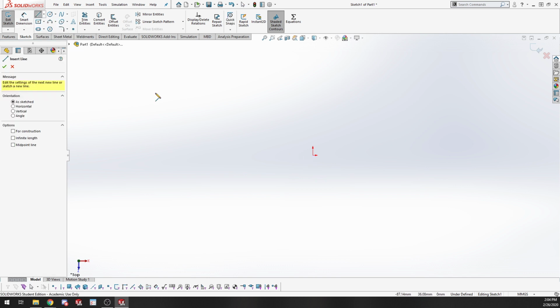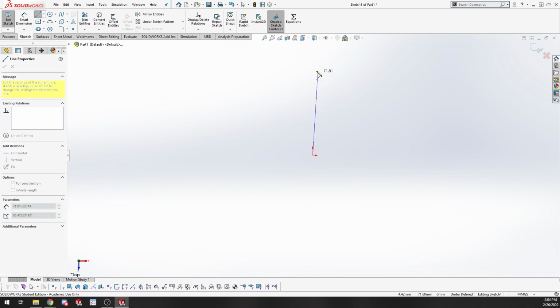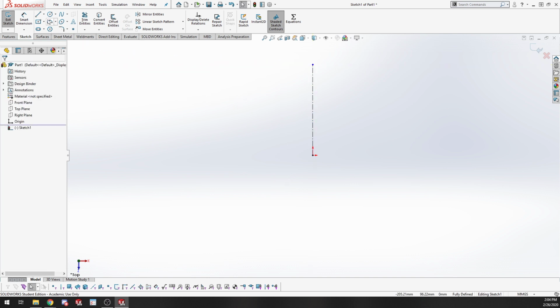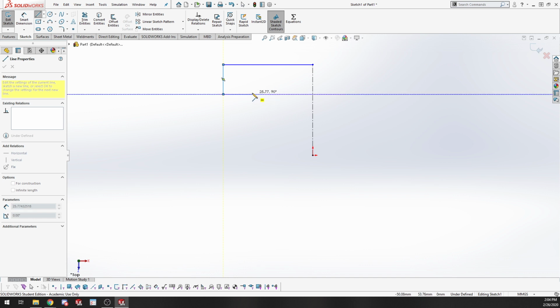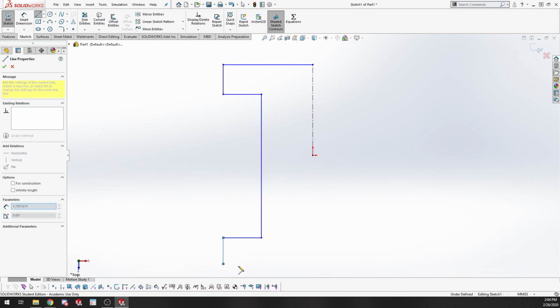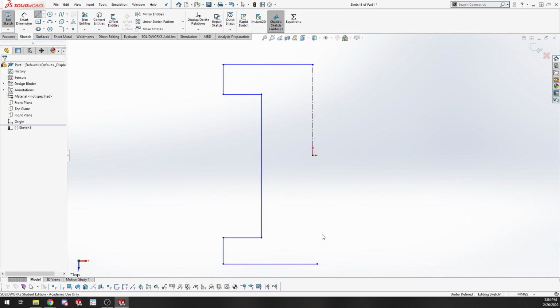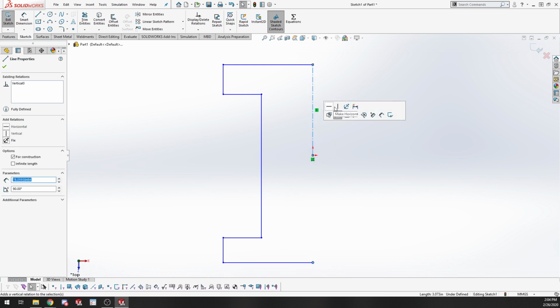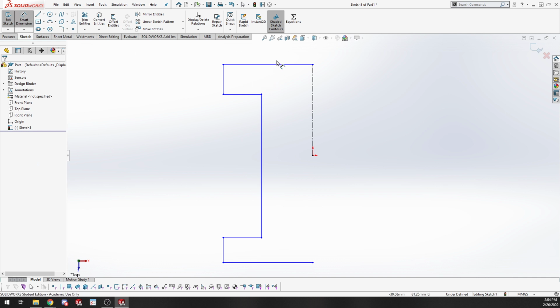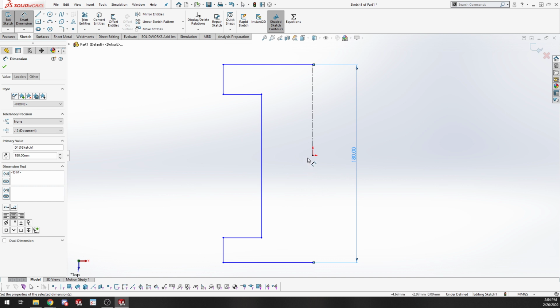So a simple construction line to start, and then, because the center of the steering wheel is a fairly simple shape, there's where my first grips come out to. I'll just make it super simple here. Just going to have 2 grips. I think the steering wheel that I designed was like 200, maybe 180 millimeters tall.